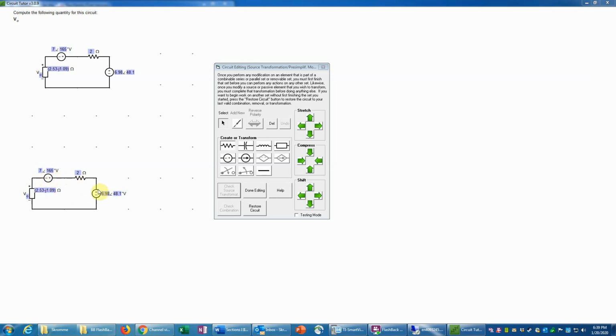If we shorted this one, though, this one would make it go counterclockwise, because here we're going to go from the high voltage through the passive elements back to the low side. Again, water flows downhill through passive elements. And so that's going to go counterclockwise, which is the opposite of this one. And so that means they're fighting each other. And it's much like if you put two batteries in a flashlight the wrong way with the two positive sides touching, then of course that wouldn't light up your bulb because the voltages would cancel out.